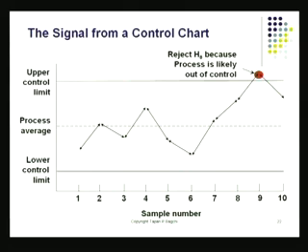Look at one chart that is shown here. It's very possible that till this point the chart was in good process control, and something exceptional happened that bumped the x bar value, and it went beyond the control limit. When you go back and investigate the process, you may find a broken tool or a stopped hydraulic line, or maybe a new person started fiddling with the machine, or the raw material changed, or voltage fluctuated and therefore the cutting speed changed.